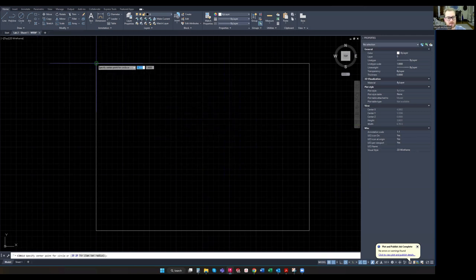So once we have our circle diameter tool, starting at this top left, we still have our grid snap on. And remember, each of these bolded intersecting lines, these grid lines, is a half inch. So that's a half inch, that's a full inch, that's 1.5 inches, 2 inches. So what we're going to do is come over 6 lines, so the first not bold line after the first bold line. Come over 6, come down 6. Right there. Go ahead and click. And we are going to type 0.75, enter, for a 0.75 diameter, 3/4 inch diameter circle.